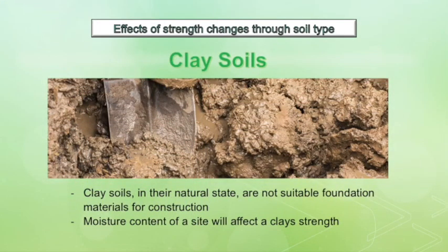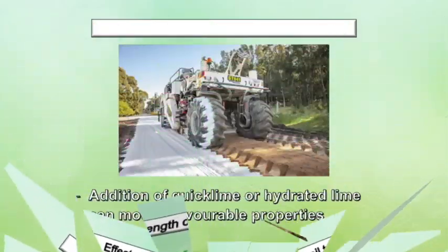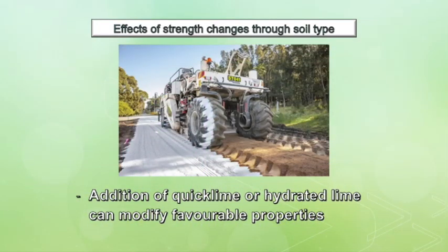Clay soils are unfavourable foundation materials due to their affinity for water, which causes shrink and swell tendencies, high compressibility, and low strength. The low strength of these high moisture content clays, or soft clays, is a catastrophic issue for geotechnical engineers as it impacts the ability of an overlying structure to meet strength and serviceability requirements. Hence, before use in construction, clay soils need to be improved. This can be done effectively by the addition of lime.